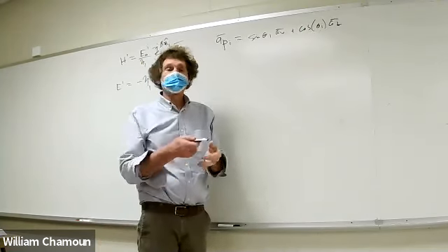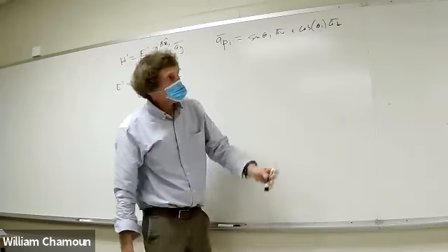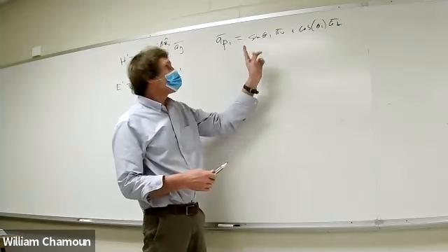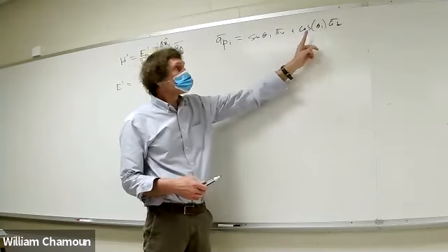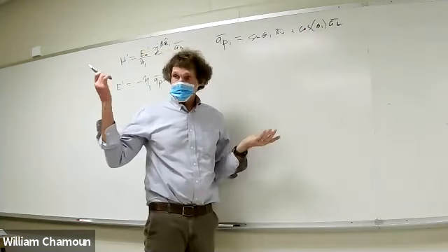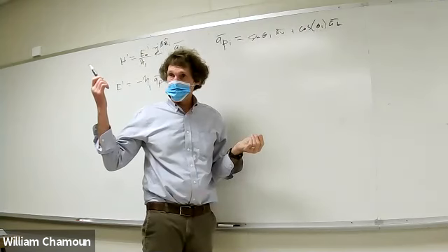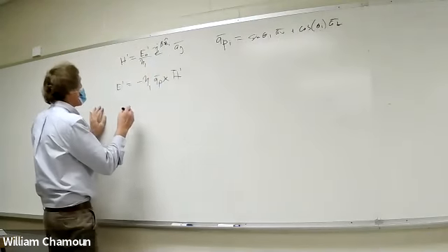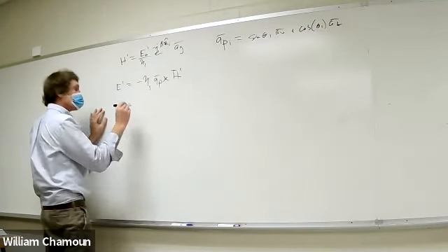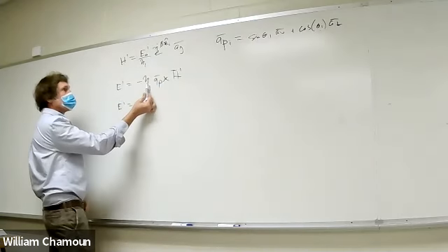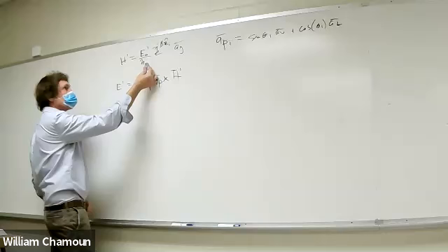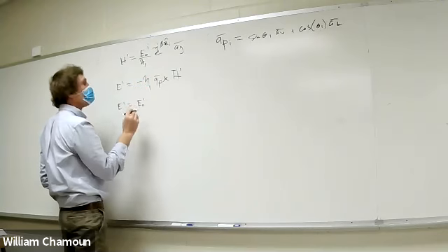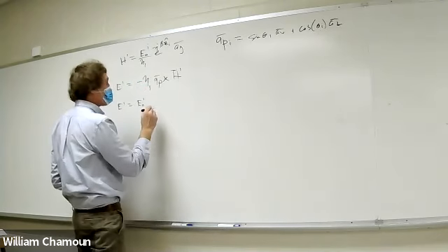That's my point. Y'all remember that? Do the other extreme. What if the angle is 90 degrees? Now it's zooming right up the x-axis, right? The unit vector would have to be AX. When it's 90, sine of 90 is 1, cosine of 90 is 0, 1 AX. Follow me? And therefore you can prove what I just said. Agreed, class? All right. Now, I have this. So I'm going to go ahead and say that E incident is equal to, you'll notice what happens when I take the 1 over eta and the eta cancel, looking at this thing as H. So I get E naught incident, as I should. Then I have a unit vector in the direction of propagation. I'm going to put it here.